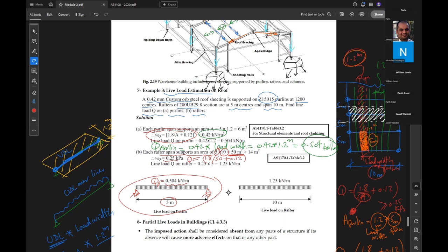So this gives us a value of 0.156. Is this acceptable, less than 0.25? No. So you should take Q equal to 0.25 kPa. Is that correct? So this note is for that. If the area is more than 14 square meters, we need to take Q as 0.25 directly.